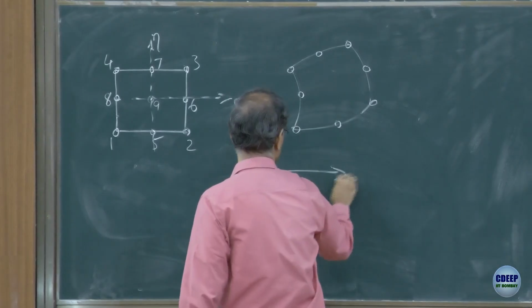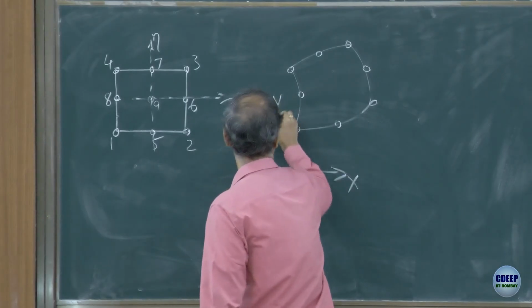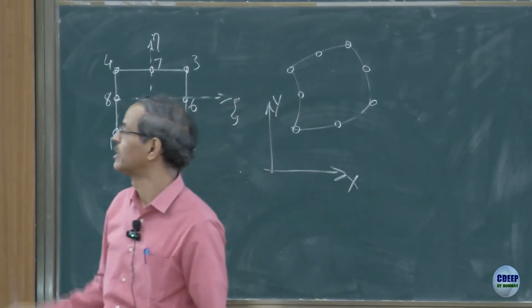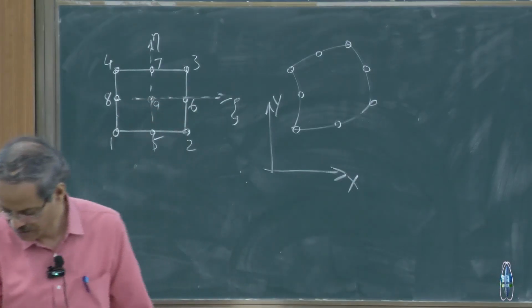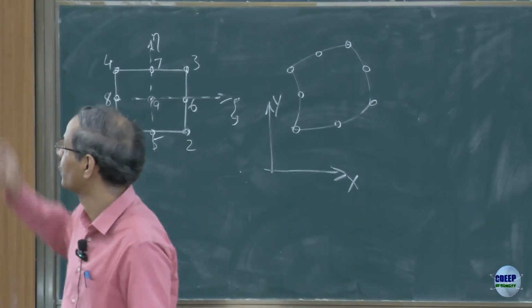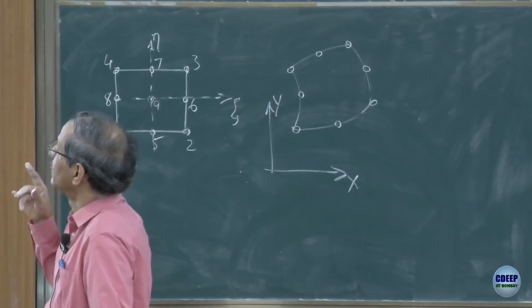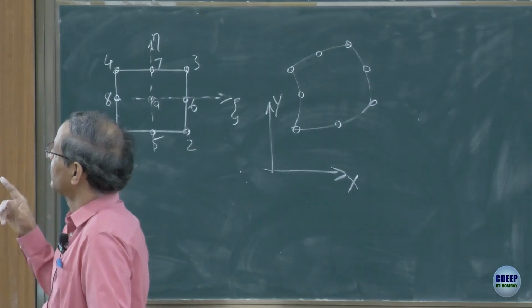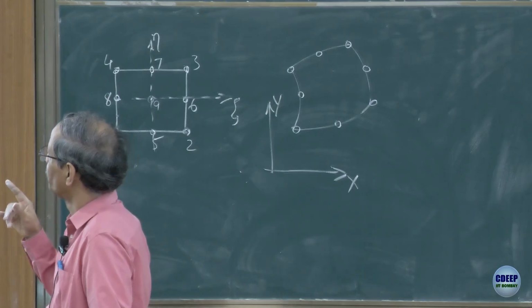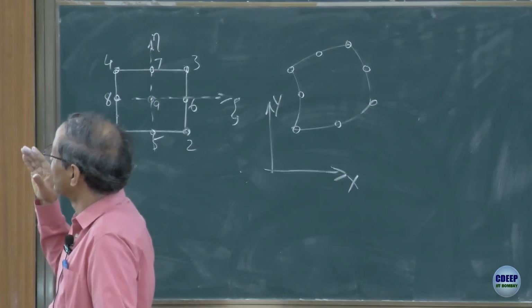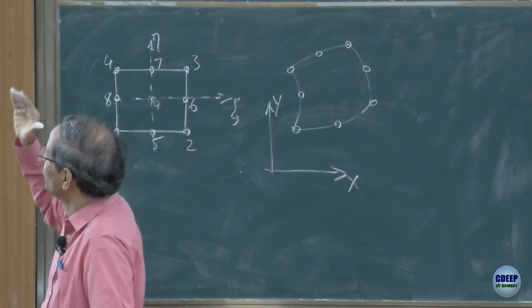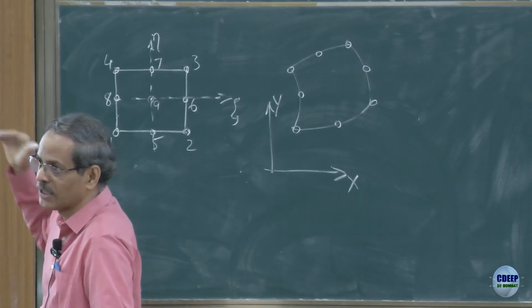in the xy coordinates. So, the shape functions etc. are given indicated there in terms of n1, n2, n3. The size of the matrices is something that you need to pay attention to, because it has 8 nodes. I am going to write u1, v1, u2, v2 etc. for all the 8 nodes.